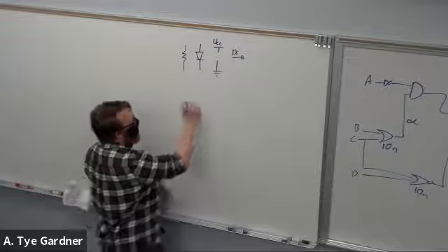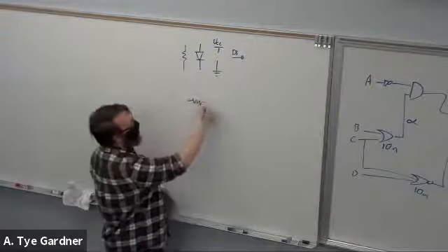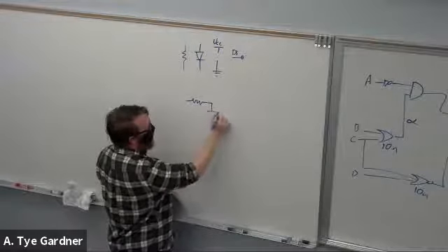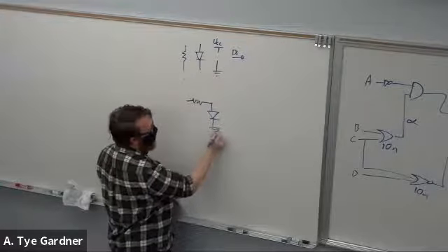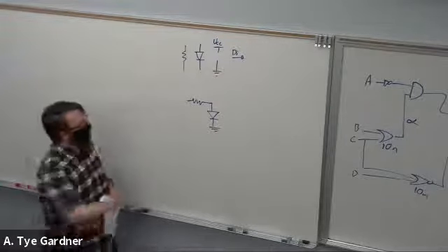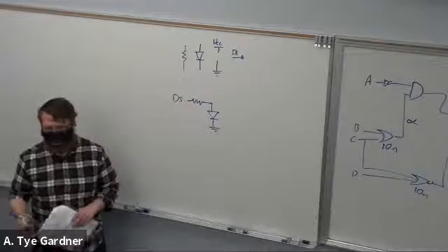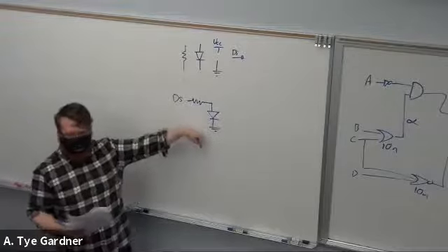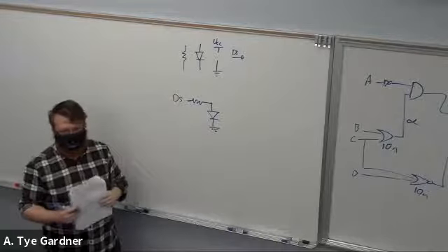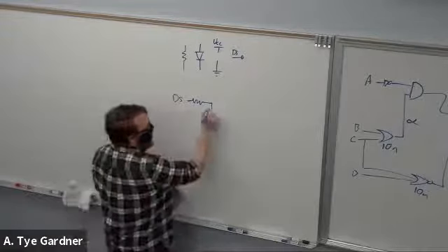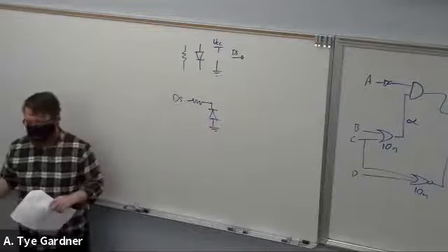Okay, well, we take a resistor. The point of this resistor is just to limit the current so we don't blow up our LEDs. It goes through an LED. And it turns out I don't need the VCC rail, I just need the ground rail. And the digital signal comes in here. Done, right? If this is a 1, we get the voltage drop, it flows through. If it's a 0, it goes ground to ground, nothing happens. If I draw the signal wrong, it doesn't turn on.